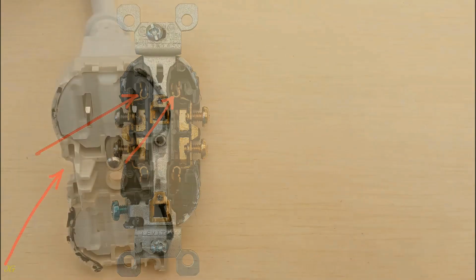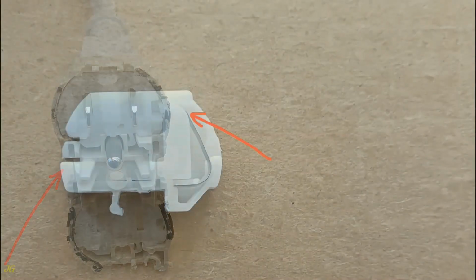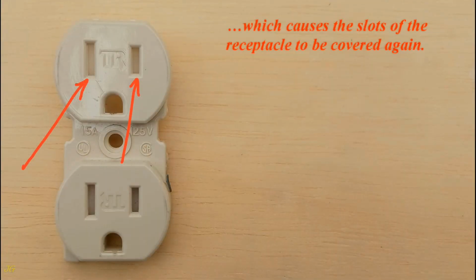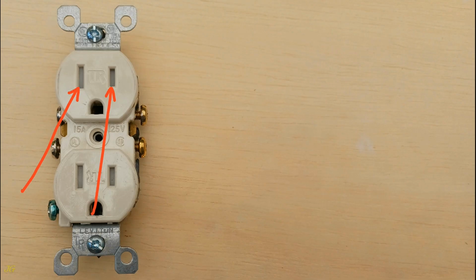receptacle. When the plug is removed from the receptacle slots, the spring that constantly presses the shutter moves it back to its previous position, which causes the slots of the receptacle to be covered again. Uneven and non-simultaneous hard pressure on the slots of the receptacle will unbalance the shutter mechanism, preventing the plug from being inserted and consequently damaging the receptacle tamper-resistant mechanism.